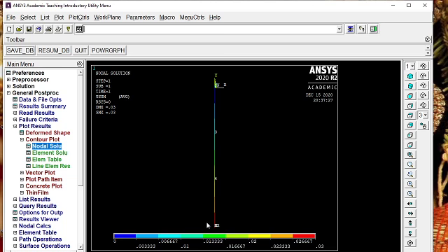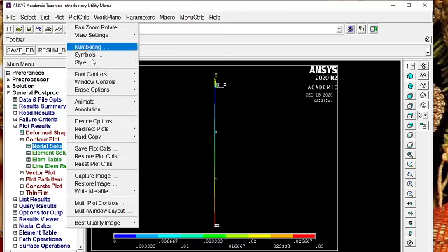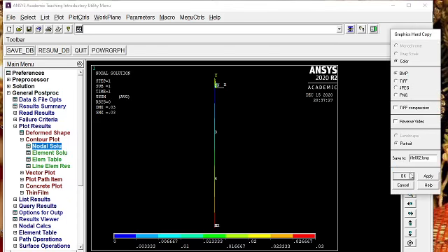So the highest deflection exists at the free node, the red mark, and the lowest is at the fixed end, 0. But normally it is not 0 at the fixed end; it is a very small deflection which is negligible, so we will not consider it. The way we calculate in finite element analysis is the same way adopted here, assuming that the fixed end is 0. Otherwise, in FEA by the penalty approach, we can find the deflection at the fixed end also, but that will be very small, negligible. Okay, I am saving this particular value also.